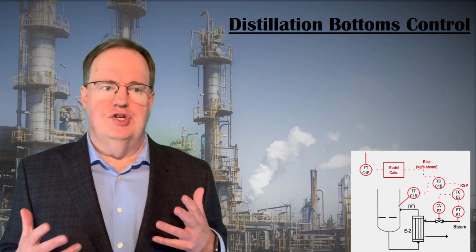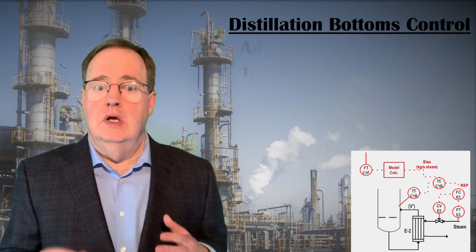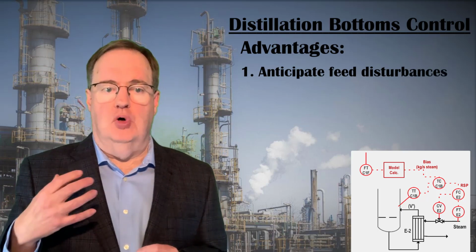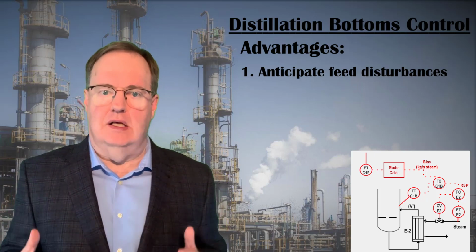What are the advantages and disadvantages of this feedforward model-based control? First and foremost, the model will anticipate and act to accommodate the changes to reboiler steam demand that a change of column feed flow would entail.